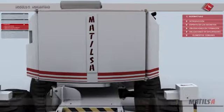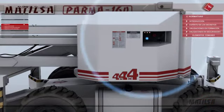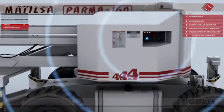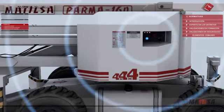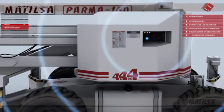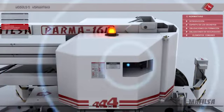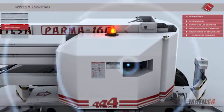Acoustic and lightning warning signals. The access platforms will have compulsory acoustic bleepers that warn of the presence and the motion of the machine. The acoustic signal is located on the base of the machine, since the warning signal is intended for passers-by. In cases where the machine is working in areas shared by other vehicles, it will also be necessary to install a rotating light signal to indicate its presence while parked at the workstation.